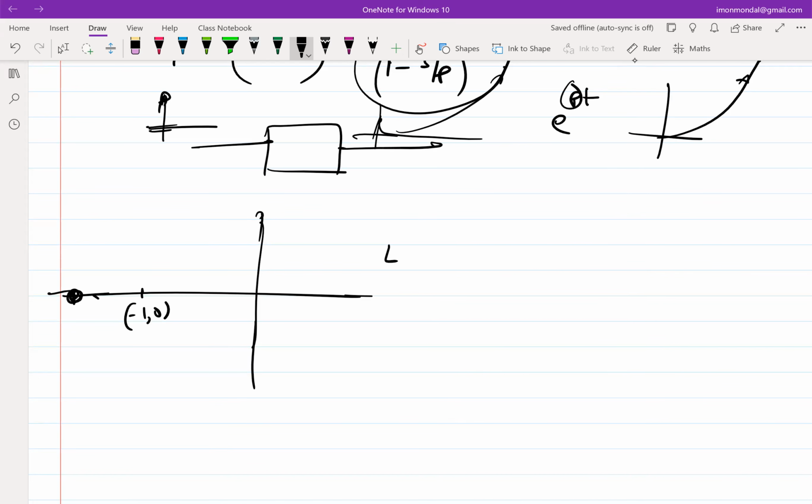I need not necessarily know whether it's stable or unstable, because it can as well be that it has gone like this, come back like this, and gone like this. It's not encircling the -1, 0 point, right? So this can still happen. So L of -2, or a specific value of L, will not give you that information, whether it's stable or unstable. You have to look at the entire plot.